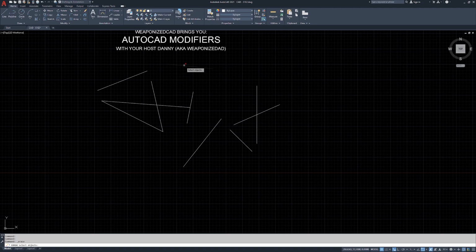Erase command. You can single click. And you're simply telling AutoCAD, all of these objects that I've selected, all I want to do is erase them. So it's a super simple command. Erase. Select objects. We've selected these objects. I'm going to right click. It just erases those 6 objects. If you accidentally erase something, remember you can use the undo command with U enter or the undo button up here at the top. I'm going to undo that.